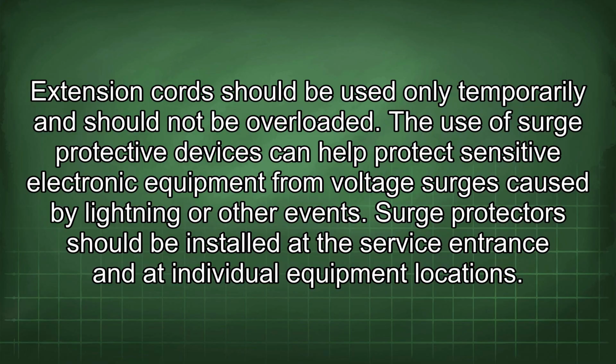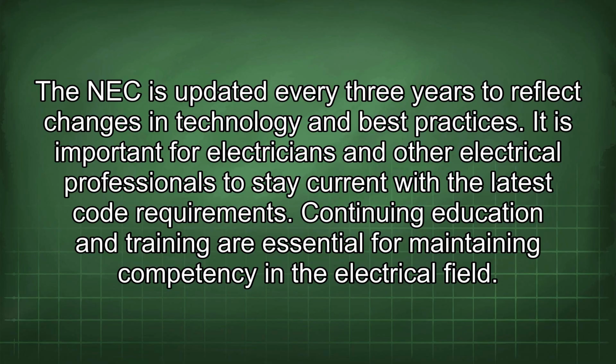The use of surge protective devices can help protect sensitive electronic equipment from voltage surges caused by lightning or other events. Surge protectors should be installed at the service entrance and at individual equipment locations. The NEC is updated every 3 years to reflect changes in technology and best practices. It is important for electricians and other electrical professionals to stay current with the latest code requirements. Continuing education and training are essential for maintaining competency in the electrical field.